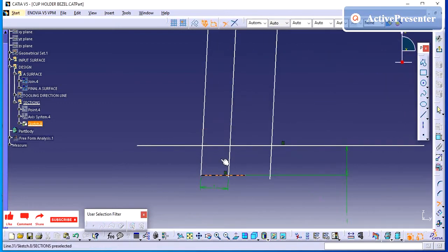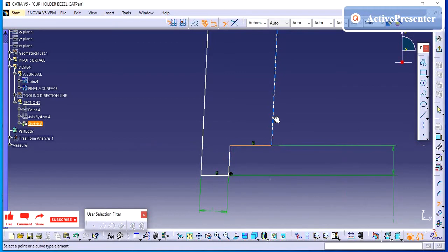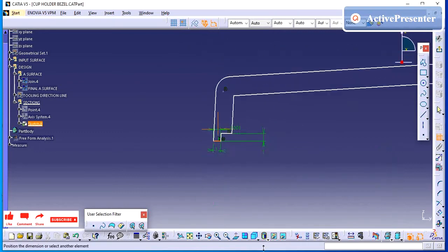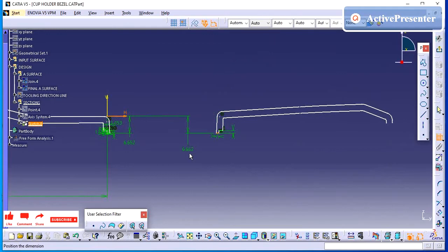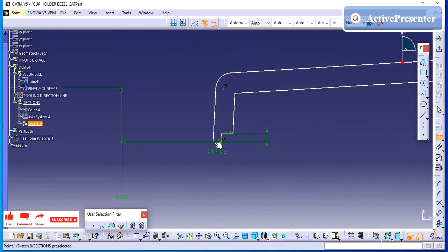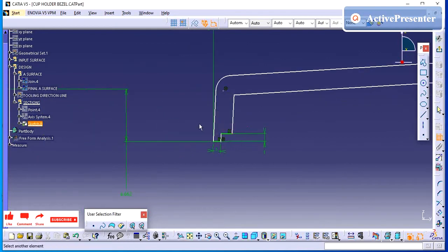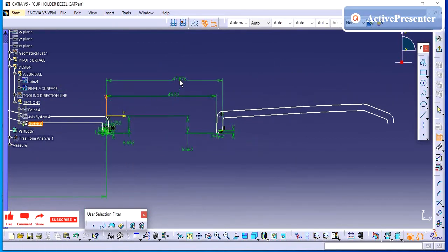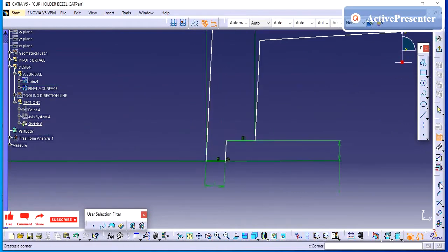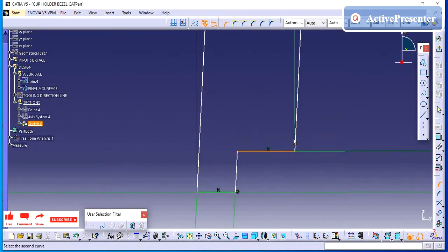Designing is different from engineering. So here we need to think from the engineering aspect. On this side also I'm not touching the A surface. Instead of creating this flange on the A surface, if you create it on the B side, it will have a see-through. So finally your design won't be proper, it won't have the proper look, and the customer won't feel good. So in this aspect you need to think and work on the part.